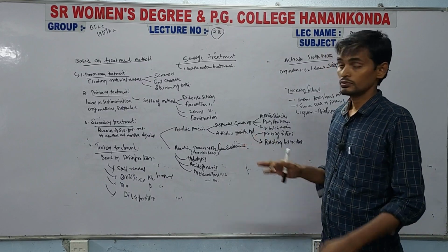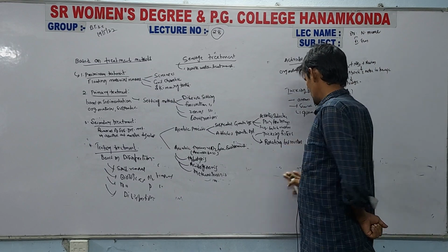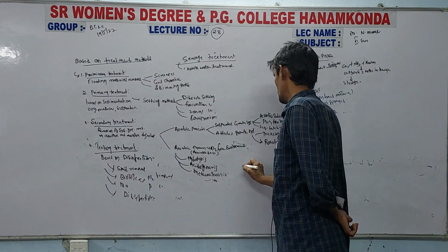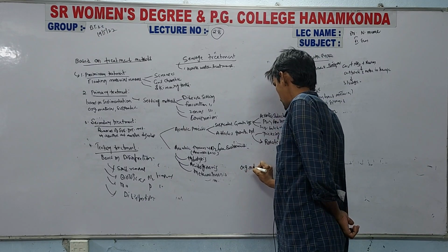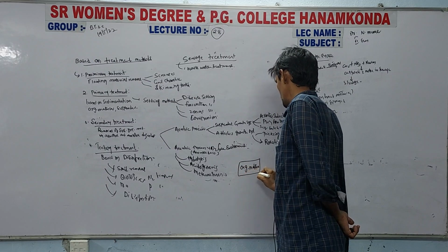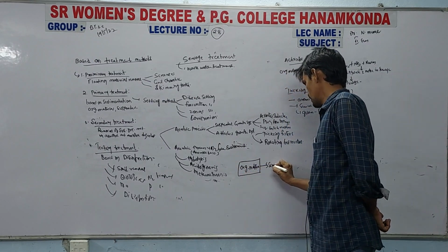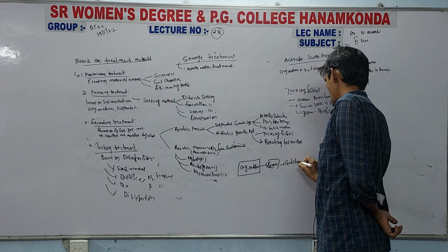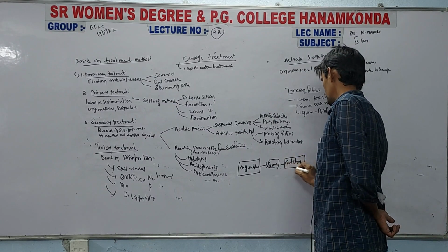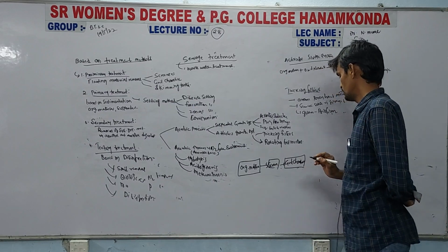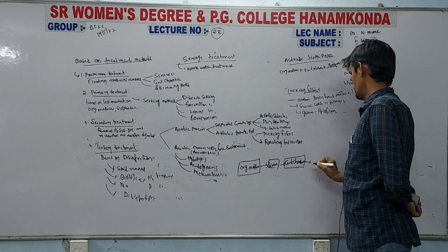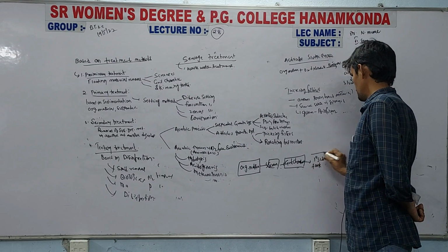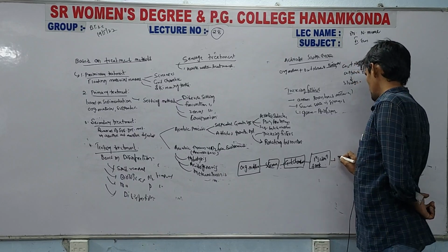So, these are the different processes based upon treatment methods. If you see the overall block diagram of sewage treatment, whatever the organic matter will pass through the screeners, grit chambers, which goes through the primary sedimentation tank, from which it goes to the aeration tank.